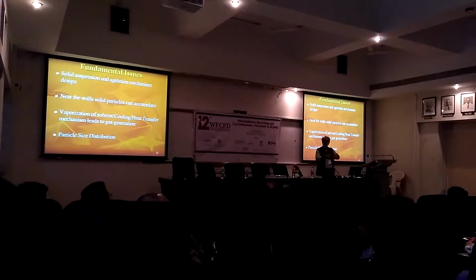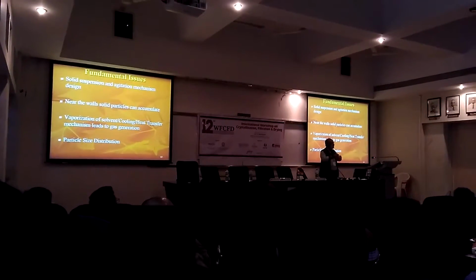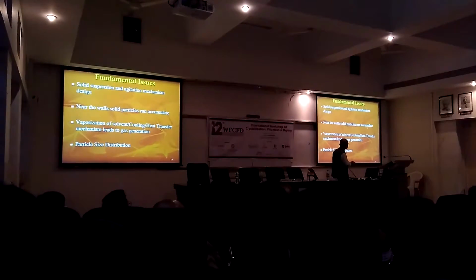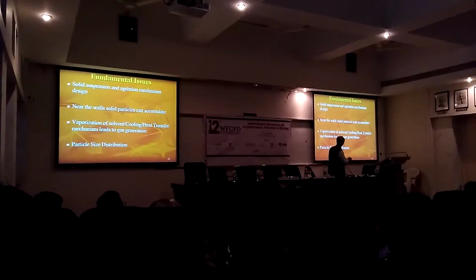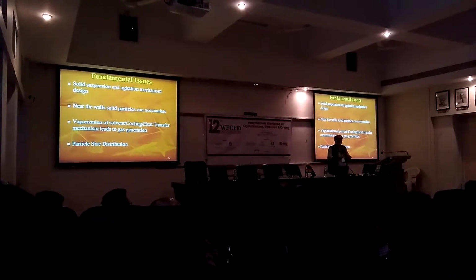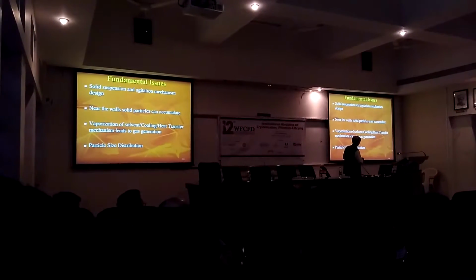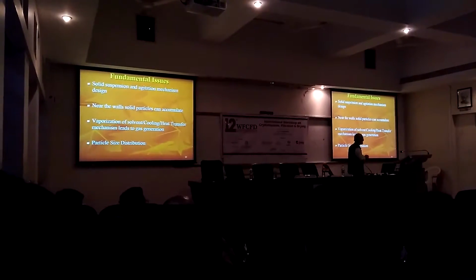So you require some mechanism by which to keep that particular heat transfer surface clean by some sort of a scraping mechanism. So near wall solid particles can accumulate and you need to keep on cleaning up this heat transfer surface so that you can keep on getting the required heat transfer, either supply or removal of heat. Vaporization of solvent, cooling, heat transfer mechanism leads to gas generation.